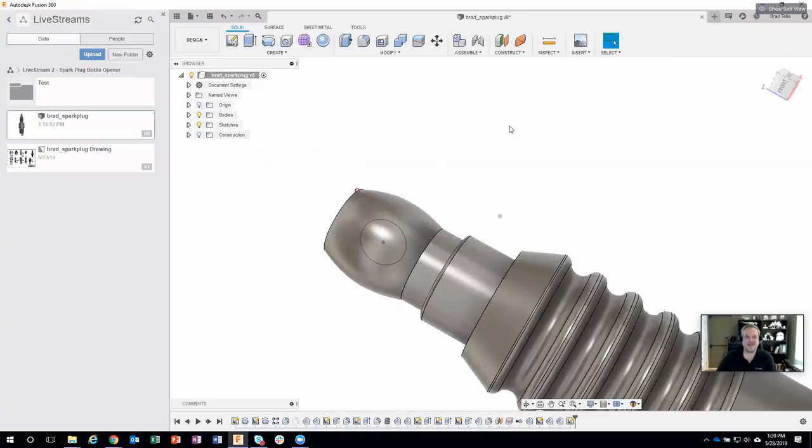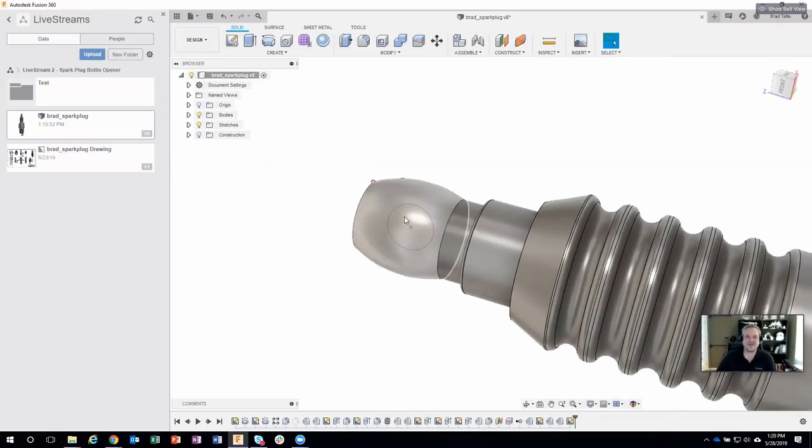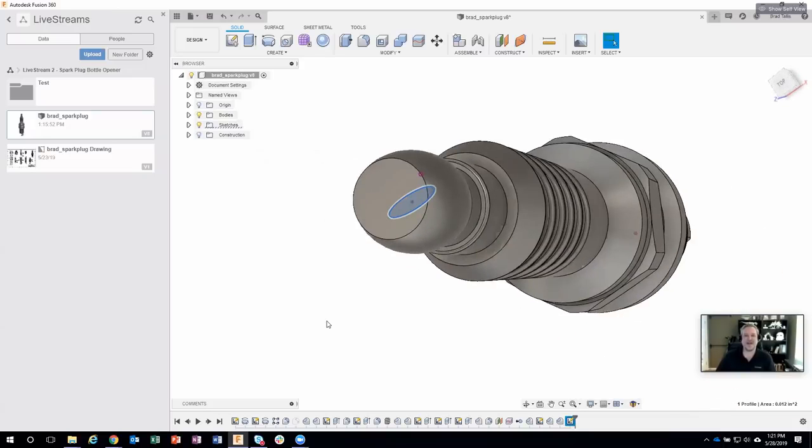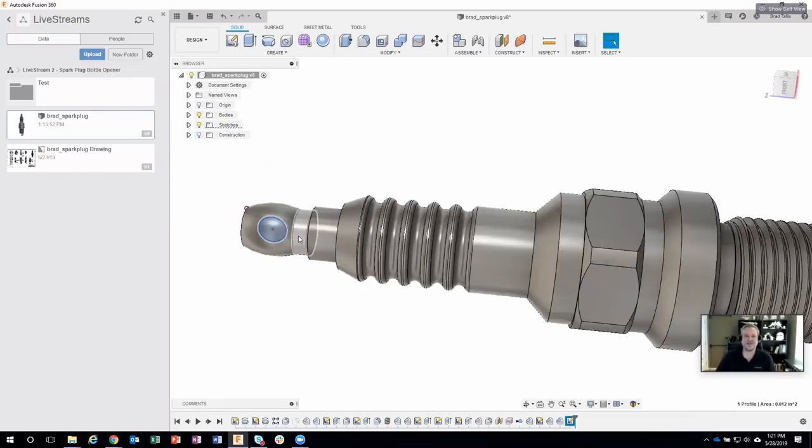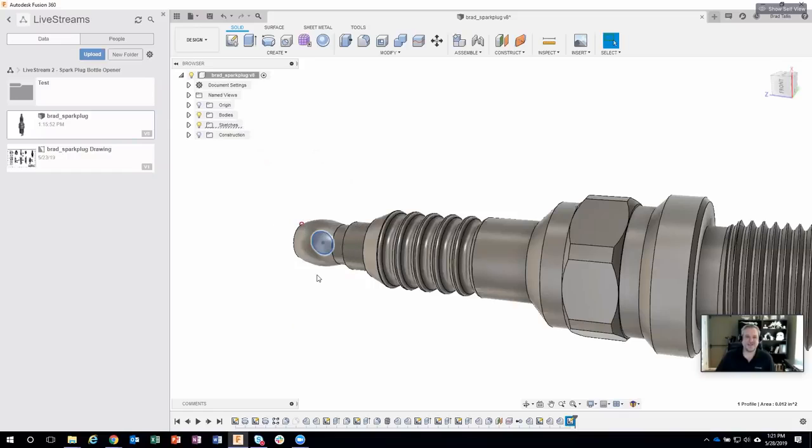So let's go ahead and machine this through. Now, I've shown this tip multiple times before, but I want to select this profile. I'm going to click on this by holding down my left mouse button, and I can say profile. So it's basically allowing me to probe through. The very front thing is the face, the next thing is the profile. So now I've selected that profile, which is kind of buried inside of that part. I'll go ahead and extrude this.